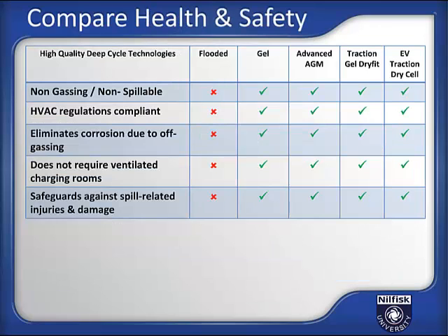So let's compare health and safety considerations as it relates to the 5 battery technologies. What you'll notice on this table is across the board, we've got a bunch of green check marks for every technology except for flooded. Why that is, is because the 4 technologies represented in green are all of the sealed valve regulated lead acid category, which is to say that they are non-gassing and non-spillable.